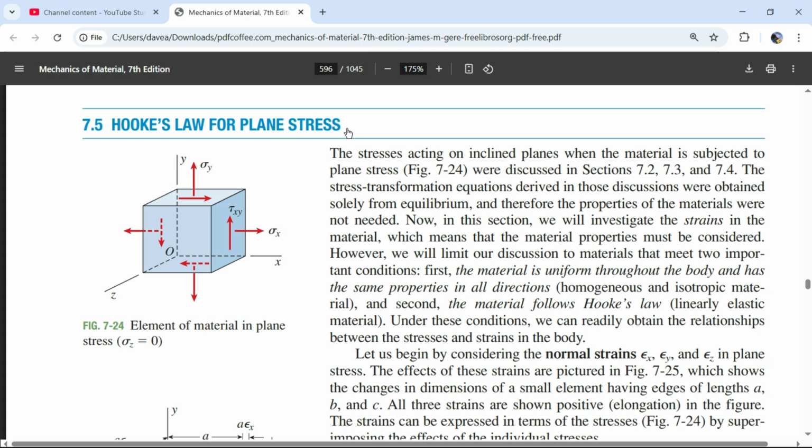And then after that, we can have our element. So now we know what the element would look like at any place on the cross section. We still have to pick a place on the cross section to take our element, but at least this is 0. It'll just have tensile stress, so it'll just have normal stress in the positive x direction right here. This will be 0. And then the game begins. We're going to take our element,